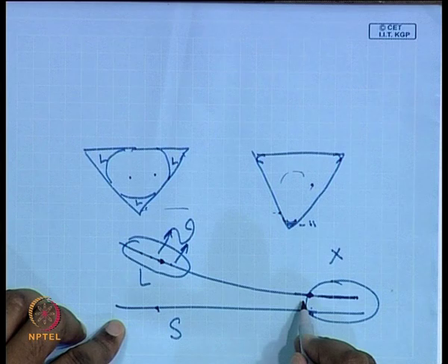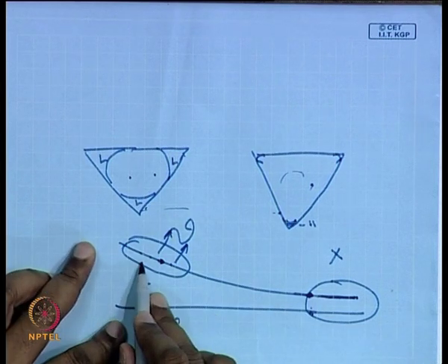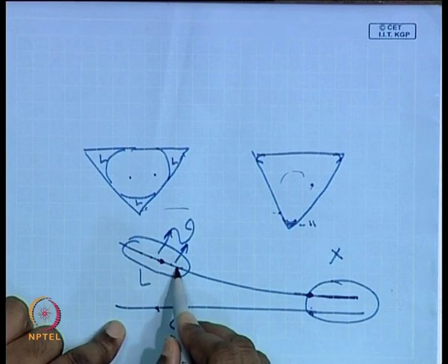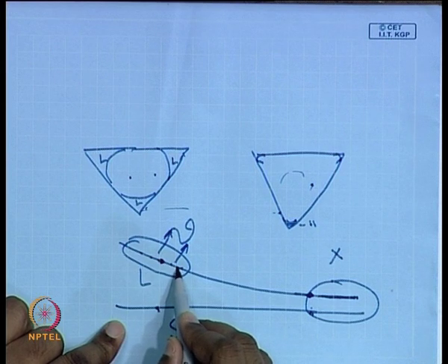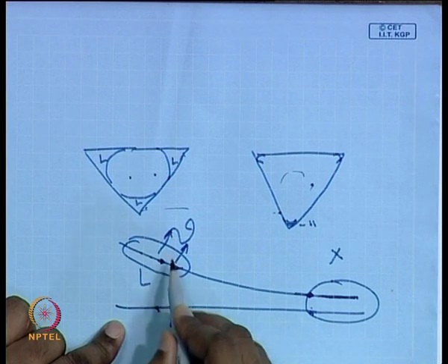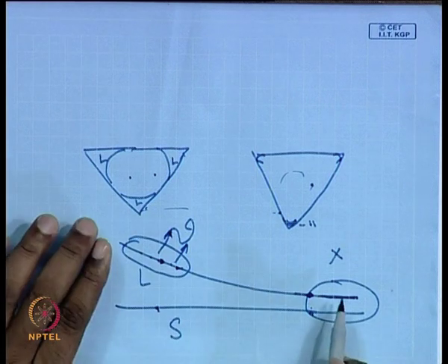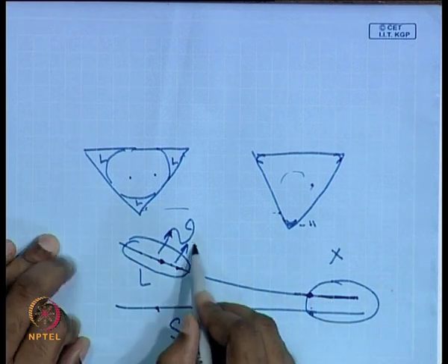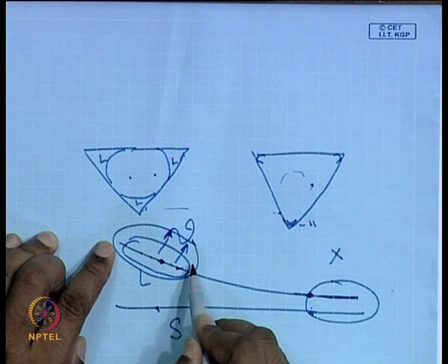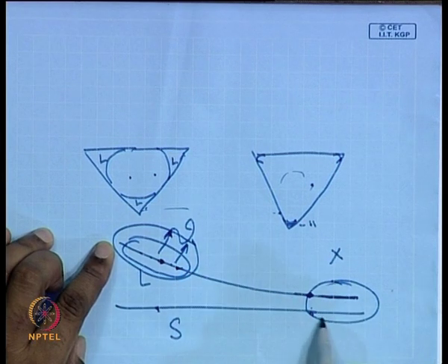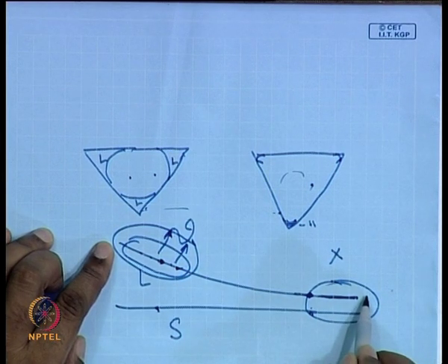or a non-wetting system. As I move towards this direction, the thickness of the film starts to increase, and the conductive resistance provided by the increasing thickness of the film will reduce the amount of evaporation from this zone. So, there exists something in between this zone where capillary forces predominate and this zone where intermolecular forces predominate.